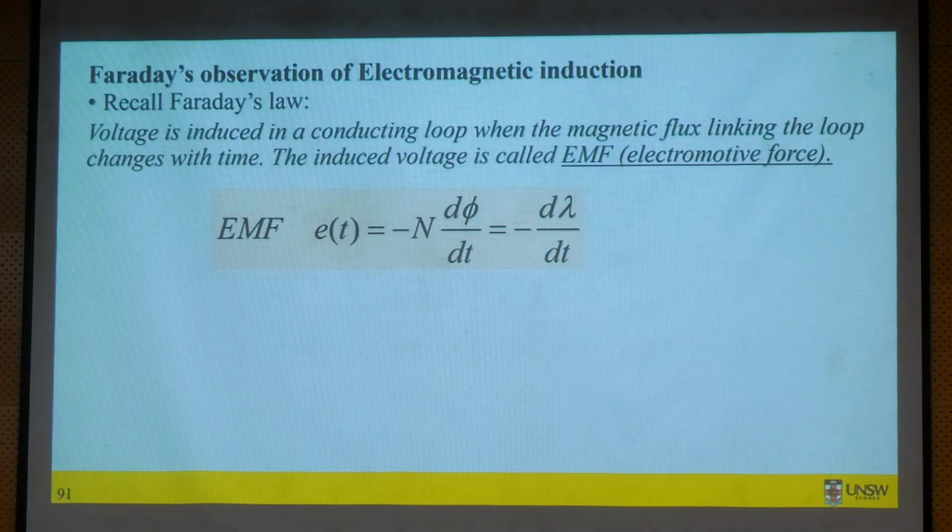And the other thing is Faraday's law, which gives us the back EMF in the machine, right? In a PM machine, the flux comes from your magnet, so whenever the rotor rotates, you get your back EMF, and this flux in the case of a PM machine is constant.